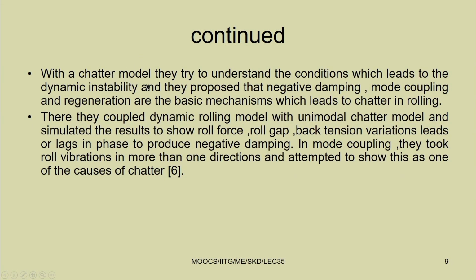With a chatter model, they tried to understand the conditions which lead to dynamic instability, and they proposed that negative damping, mode coupling and regeneration are the basic mechanisms which lead to chatter in rolling. Already we know how to analyze a system with negative damping.